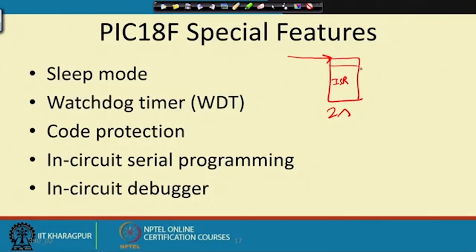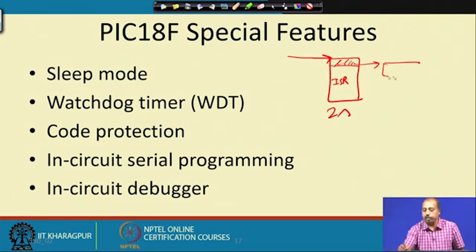To do that, at the beginning of the ISR, apart from writing the ISR code, we also start a timer. Then at the end of the ISR, we disable the timer.